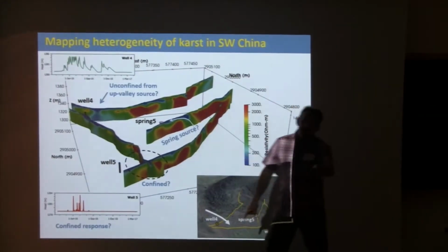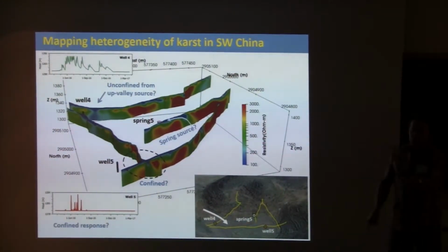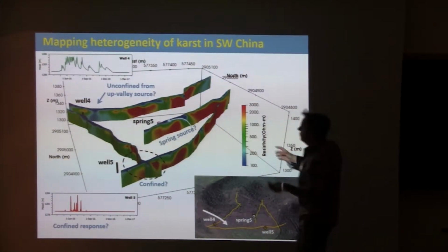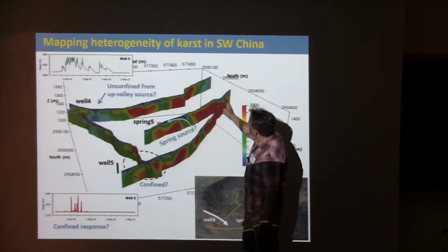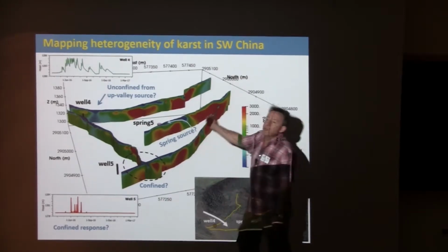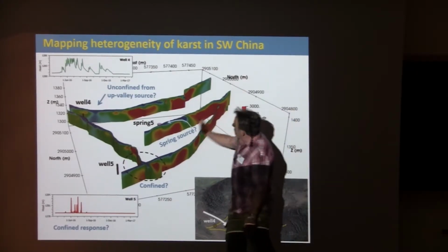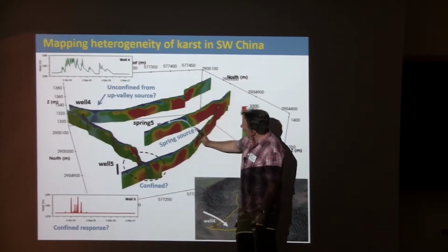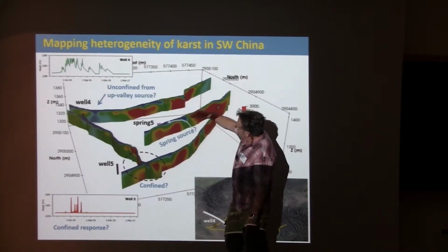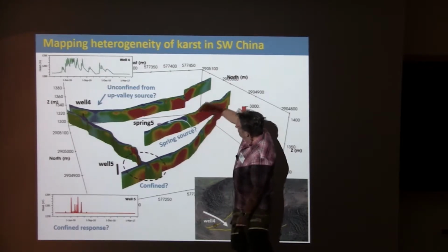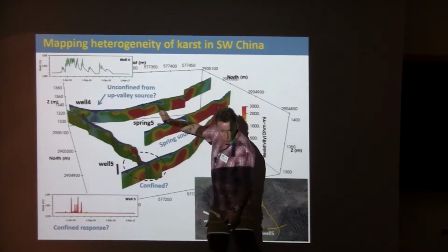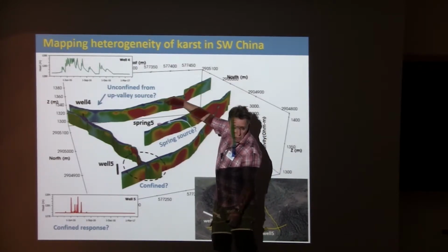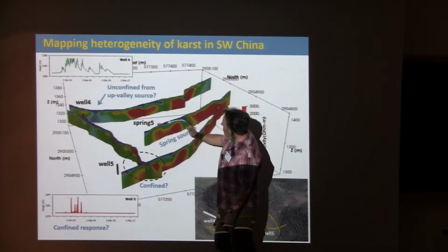Actually, this is a really important point with the geophysics, because you do have to wear the right glasses to be able to interpret this. But what you can see here is that the red zone is a very resistive area, and there's a break in it, and there's a break here too. And we can see this very conductive zone on the surface that we don't see further upstream. So there's a contrast going downslope, not only at shallow depths, but also at some depth here.